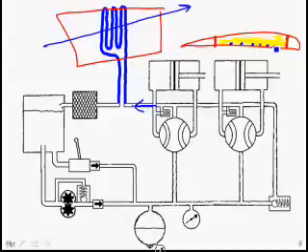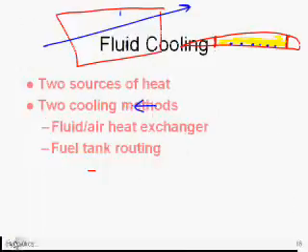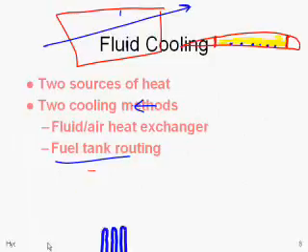Now it's going to warm the fuel up, but if you take AS311 turbines, you'll find out that warming the fuel is okay. It prevents water inside of the fuel from freezing into ice particles and clogging filters and stuff like that. So it's actually good to warm up the fuel. And this way the heat energy leaves the hydraulic fluid and it gets cooler. So this is a very common method in transport category jets, big biz jets, and big turboprops to cool the hydraulic fluid down by running the fluid through the fuel tank.